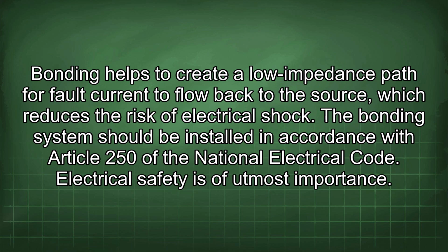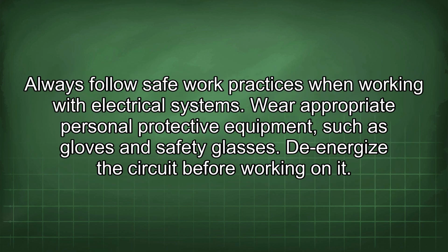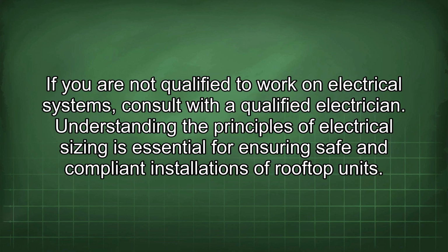Electrical safety is of utmost importance. Always follow safe work practices when working with electrical systems. Wear appropriate personal protective equipment such as gloves and safety glasses. De-energize the circuit before working on it. If you are not qualified to work on electrical systems, consult with a qualified electrician.